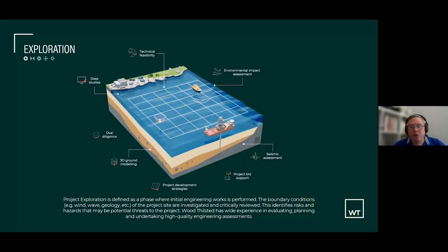Cone penetrometers and borings will give you different types of data, and you'll do a variety of those at various locations throughout the project site. You'll also draw back samples from some of these sites so that you can take the sample to a lab, get the exact characteristics of that particular layer of soil at that depth, and then that will correspond to the data that you get back from the cone penetrometer and the borings.